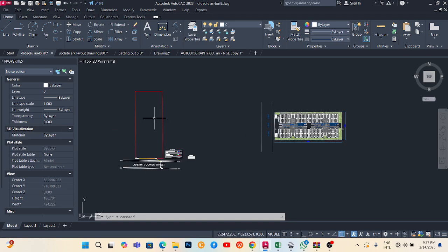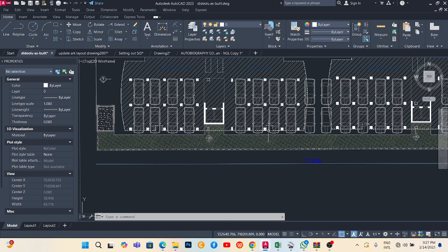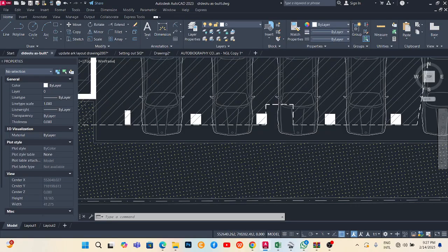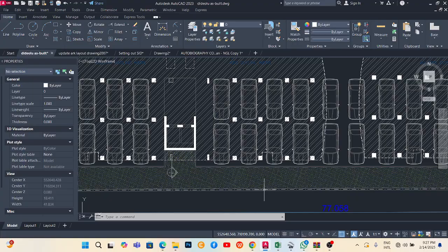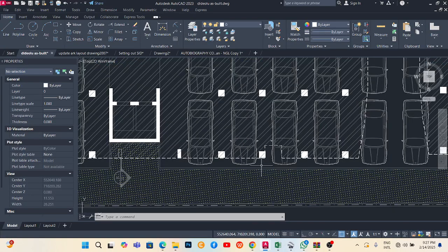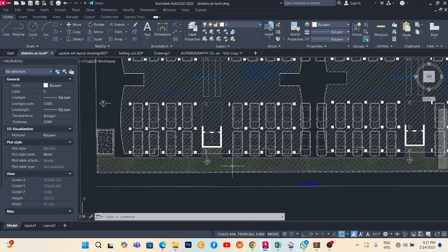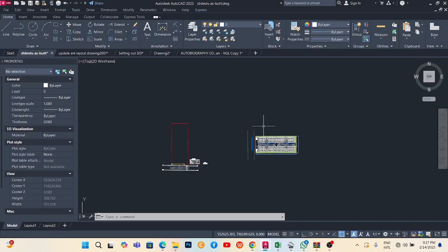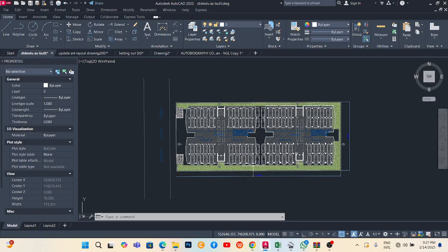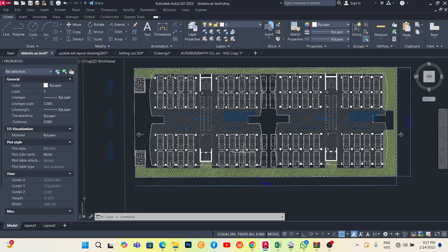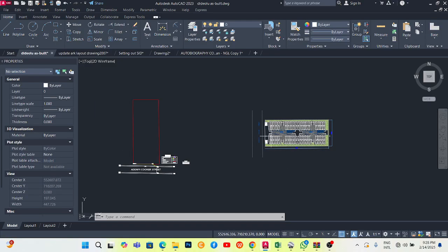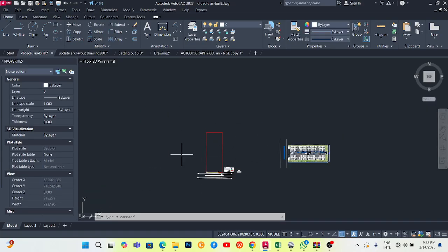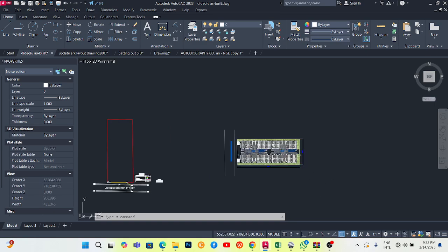Let's say the offset that you want from this building to the wall fence here, what the architect wants, is not visible. Let's say from this column here to the wall fence, the offset that the architect wants will not be visible. Those are the red flags that we need to send to them so that they can adjust from their end. It might be that we'll just tell them what is existing there and they will know how to manage it themselves. So I want to quickly superimpose this architectural drawing on this as-built so that I can see the difference.